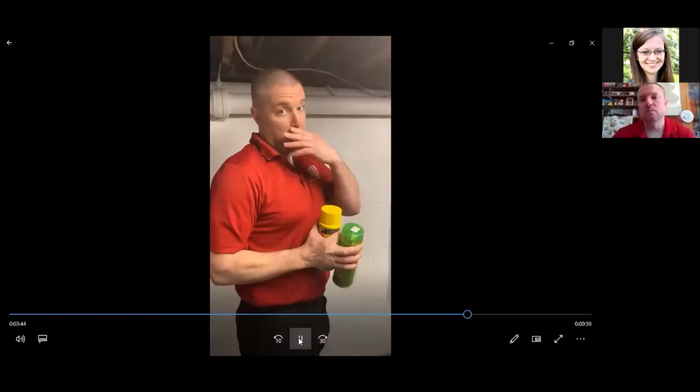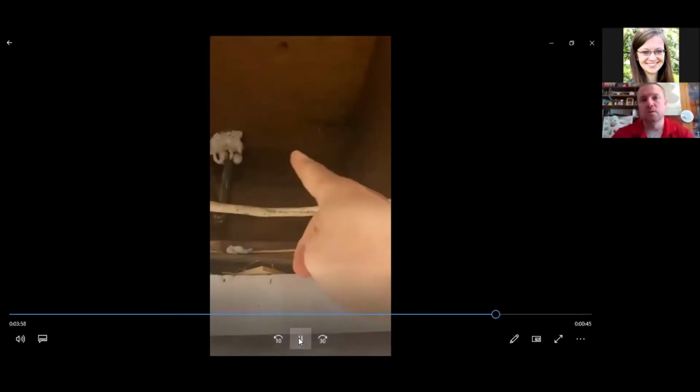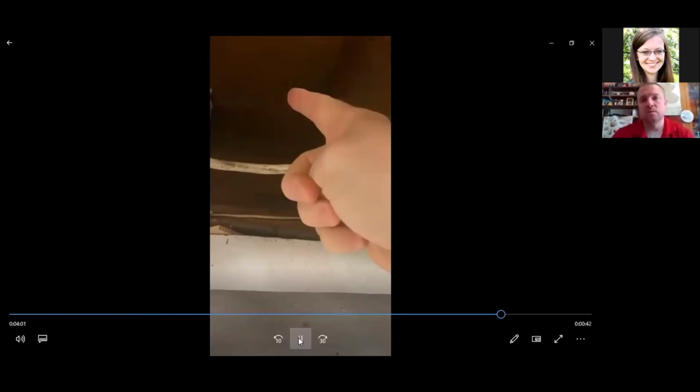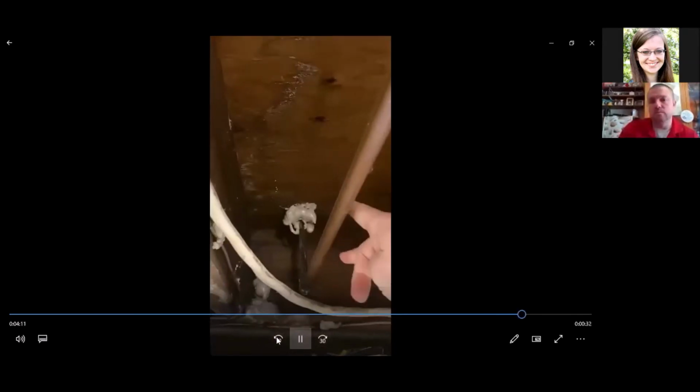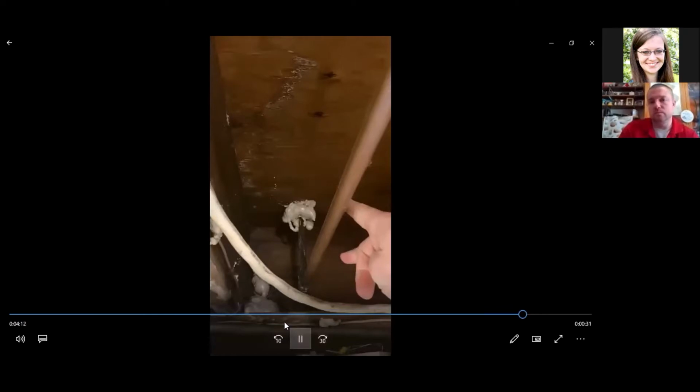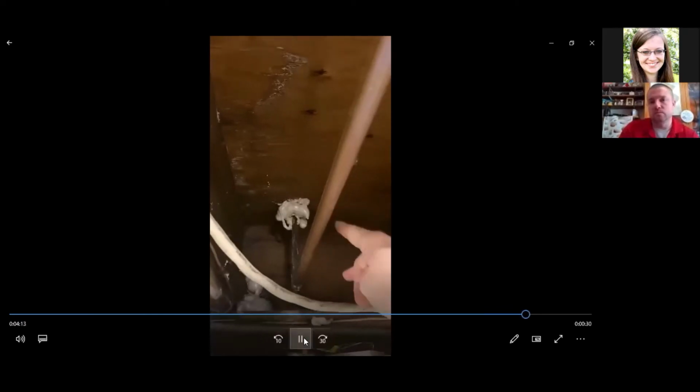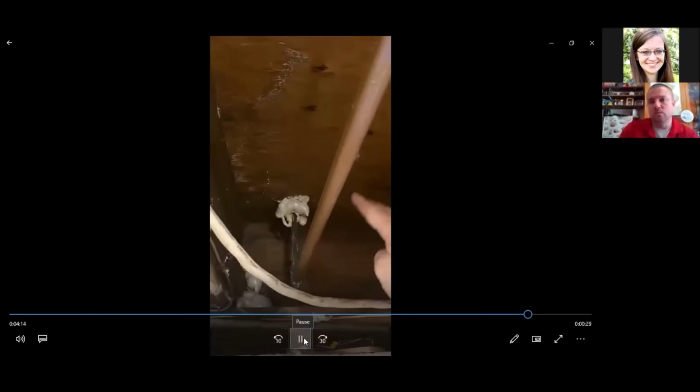So I just want to show what I've done here. Here is a plumbing penetration, an electric penetration, and then that's another plumbing penetration that goes to the first floor. I want to reduce the airflow from this cold, unconditioned space upstairs. This is the warm water pipe that goes up to the first floor. I wanted to insulate that so I don't have airflow going up through that.